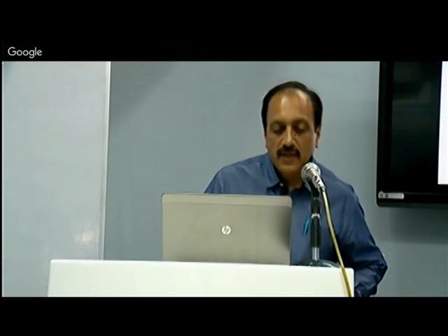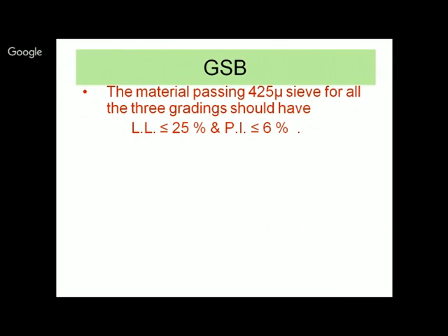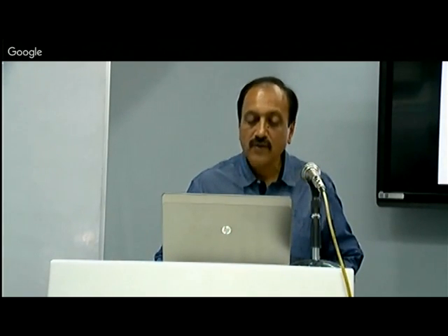Now, what is the stability? You had talked of CBR value, and now we talked of stability. CBR is the strength parameter, but as we said, due to certain issues in say subgrade, if undulations take place which will not conform to good performance, so stability of any material is desirable, which would resist those kinds of phenomena from taking place.